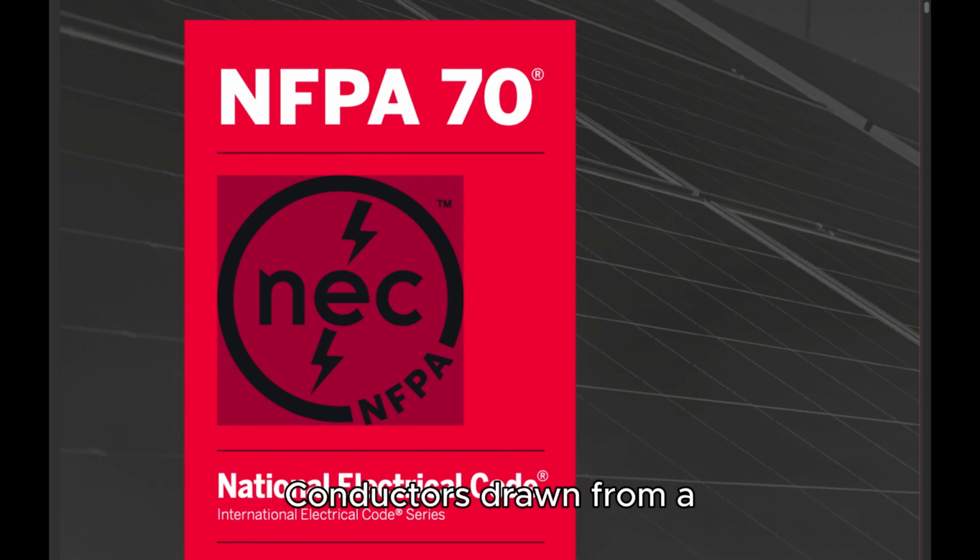Conductors drawn from a copper-clad aluminum rod, with the copper metallurgically bonded to an aluminum core, where the copper forms a minimum of 10% of the cross-sectional area of a solid conductor or each strand of a stranded conductor.